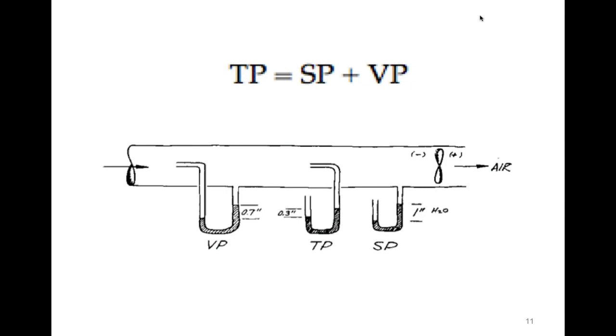So the static pressure here is -1 inch of water. Okay, we could have called that PSI. We could have called it a million other things. This is a really convenient way for us to describe this. Okay, so static pressure acts in all directions. You have static pressure in a balloon and you blow it up, right? In every part of it, the pressure is the same, and it's acting in every direction possible.